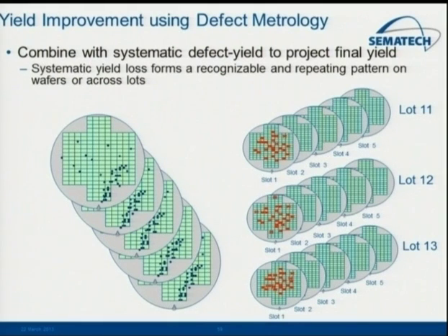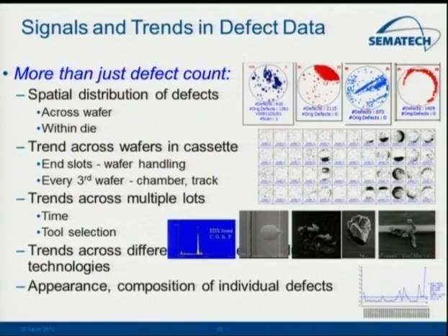And this is another example of building up defects, but in the interest of time, I'll skip over that. So you try to put all this information together. You're trying to do several things with the data that you're collecting when it comes to defect inspection. You're trying to find out if your tool's bad. You're trying to find out if there are characteristic things occurring in your process, and that some of these may be related to the tool.